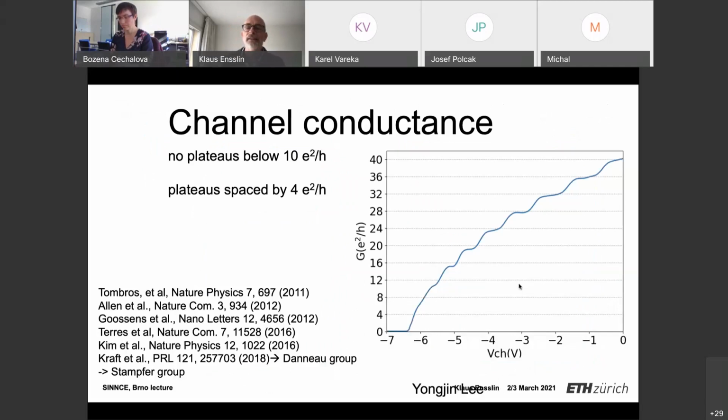And what we find is that the conductance as a function of this little gate voltage on top, all the other gates are fixed. Back gate is fixed. Split gates are fixed so that you get your gap behavior. You see that the device can be pinched off, zero conductance, and then it starts opening up, and then you see these wonderful plateaus here.